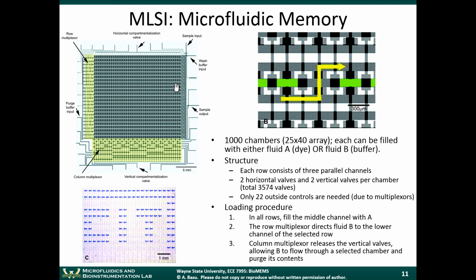So, Priyan, you'll find this interesting, I think, also because it is somewhat related to the project that you're working on right now. It's electrical memory. There's something called row column addressing. If any of you have looked at how RAM, random access memory, or flash memory works, if you want to store a piece of data, you have to tell the chip that I want to store this piece of data in row X and column Y. And it goes and stores the data into that specific area within your flash memory chip.